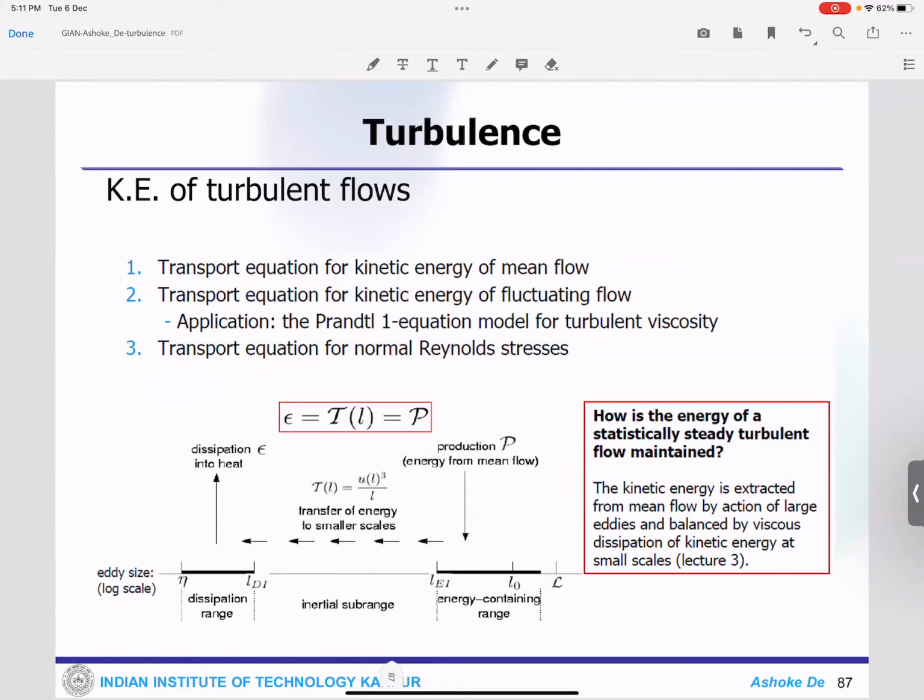And sir, for example, sometimes in simulations of turbulent flows, generally people go with the RANS study, like steady RANS. So how good an approach is it to solve a turbulent flow? Yes, the question is a very good one, but it's also a generic one, because whether steady RANS is applicable or not depends on the particular flow of interest, what you are solving.